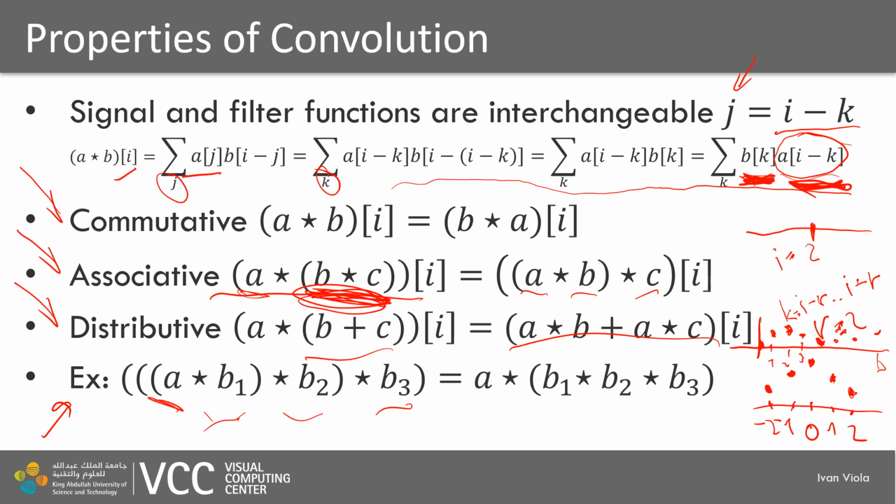And instead, this would mean that we have to perform a lengthy convolution 3 times with 3 different filters, always, and the output of one convolution will be input for the other one. Why don't we instead rather create just one filter as a convolution of the 3 filters and then perform the convolution with a long signal afterwards just once? We will save a lot of time thanks to the associativity principle.